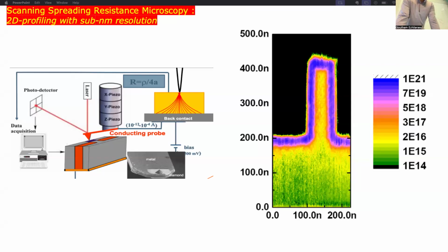Question regarding ion implant. So for the doping, do we have to use the deposition annealing method, or could we do MBE or ion implantation? You can do any method. You can do diffusion, you can do ion implantation, or the way I showed it is you can use a poly to dope it. There are many ways to do it.